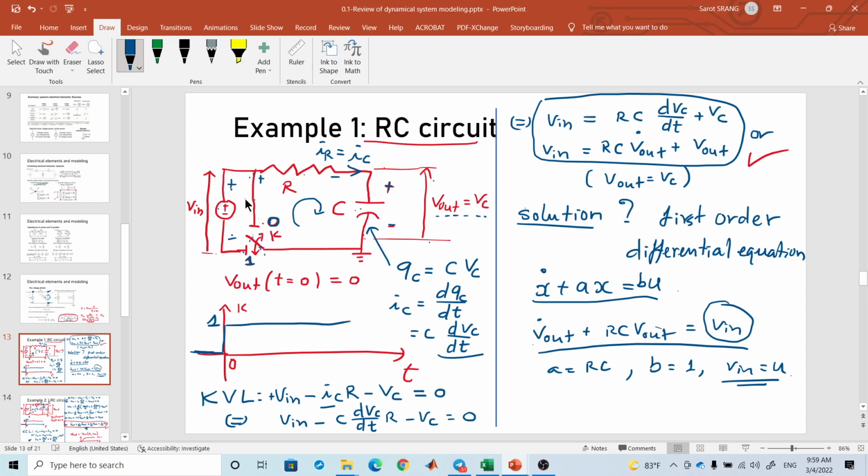But what if you don't have this? Sometimes when you make the model, you're very careful with the actual circuit. If you want to build an actual circuit to validate your modeling, and then you forgot this part, when you open the circuit here, it means you cut off the voltage, 12 volt for example. You just open it, so the capacitor never discharges, right? The voltage is still there. Be careful not to touch it. You can get electrical shock.